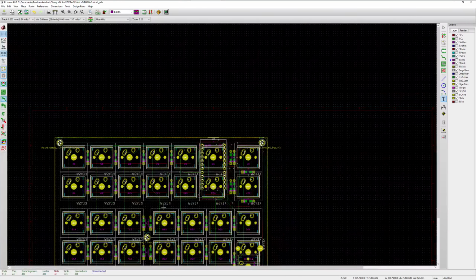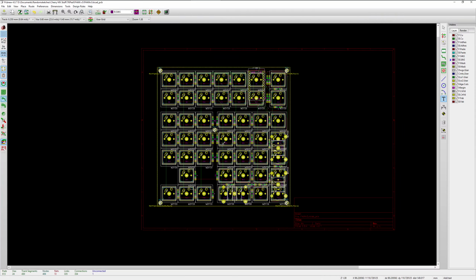Now we want to add some more pretty things. We can, but we really don't want to add a silk screen on the back, because if we do, we're going to cover up our key assignments, our key map assignments of the K numbers and the D numbers, which is why we filled them in the first place, if you had to do some diagnostics, or if you wanted to do some key mapping and that kind of thing. Of course, that leaves us with the front. So we go to our front silk screen layer, and then we can put down stuff.